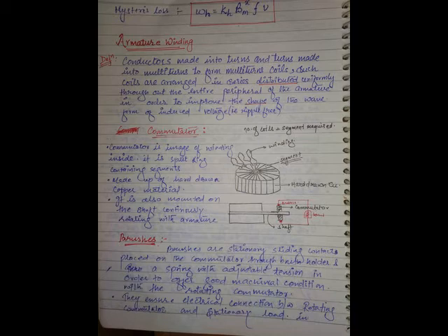When the same machine is acting as a motor, mechanical output is collected across the shaft. So finally, to give mechanical input or to collect mechanical output, we are using the shaft. The armature is keyed to the shaft to give or collect mechanical power. And bearings offer the rotation, because the yoke is a stationary part. You have to make the armature inside rotate, so through bearings you will connect it.